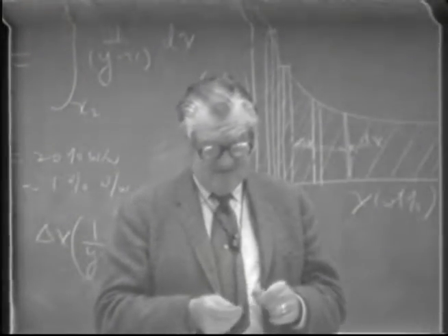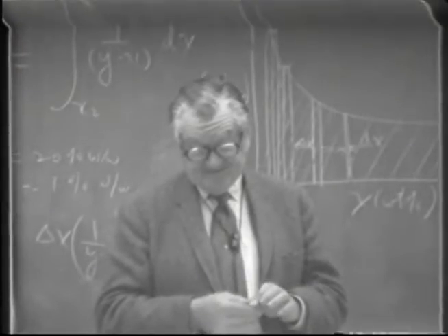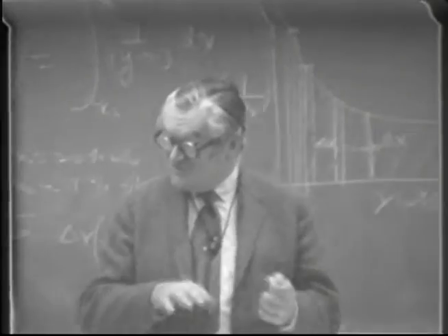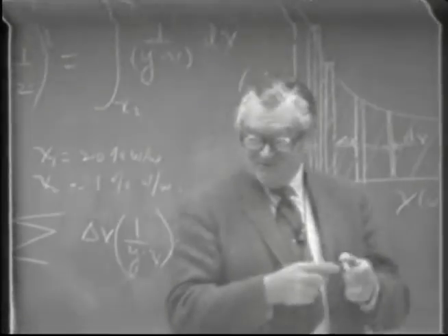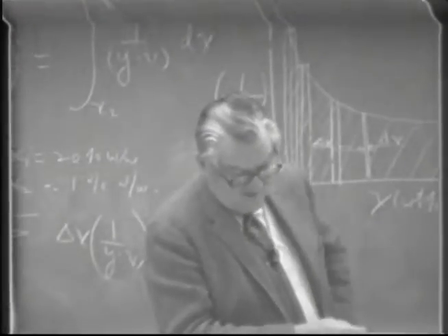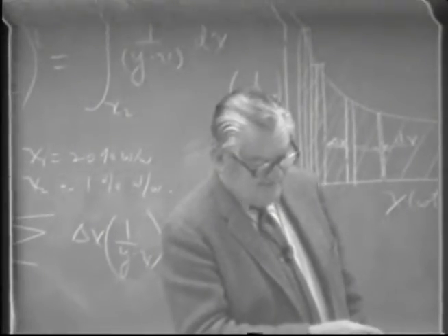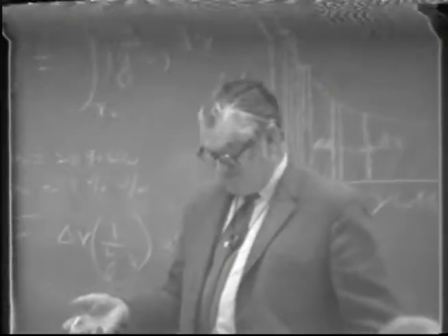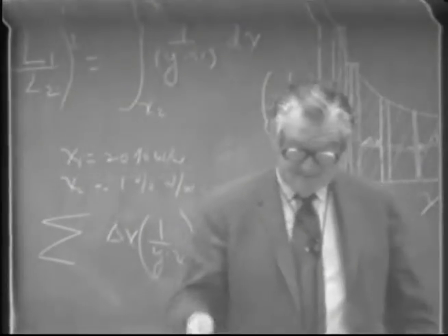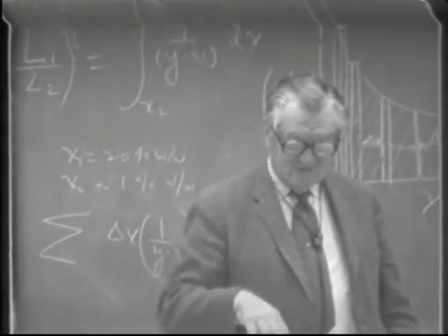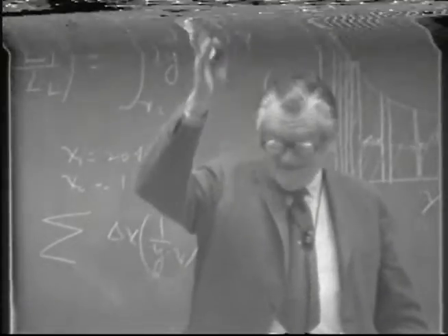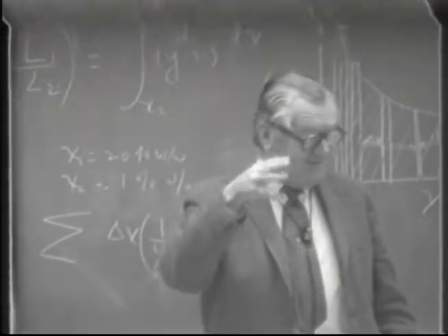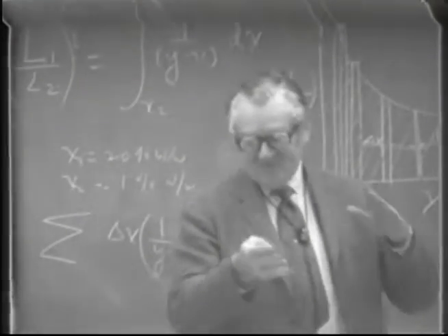it looks to me like you're running an awful lot of water in there. There's no flow meters, but just the visual appearance of churning of the liquid in there showed it was a pretty high water rate. And so I said, well, why don't we turn down this water valve to see what happens. In the meantime, we walked on up the stairs to inspect the condensers. And lo and behold, when I came back down to the fusel oil decanter, here was a